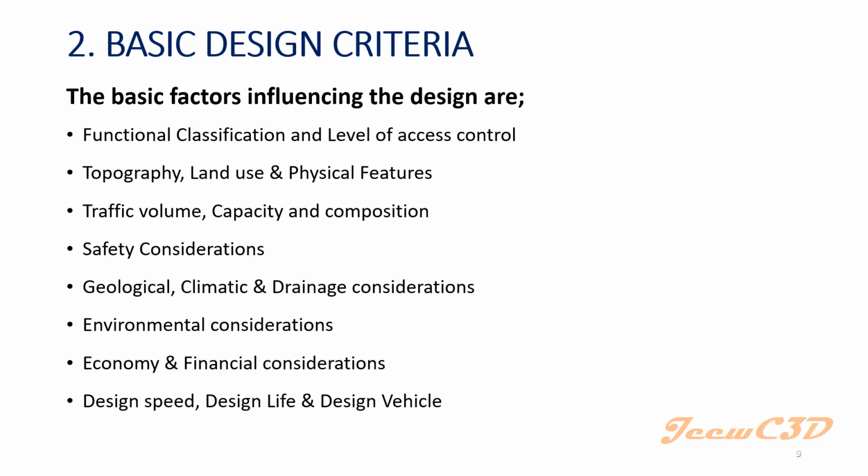So then what is the capacity of that road? How many vehicles can be accommodated in that road section. If it is a smaller road and there are so many vehicles coming, the capacity of the road is small, so your road will be getting congested. So you have to think of the capacity of your road. Depending on the capacity of your road, you have to accommodate 1 lane, 2 lane, 3 lane, 4 lane. Likewise, how many lanes you have to use.